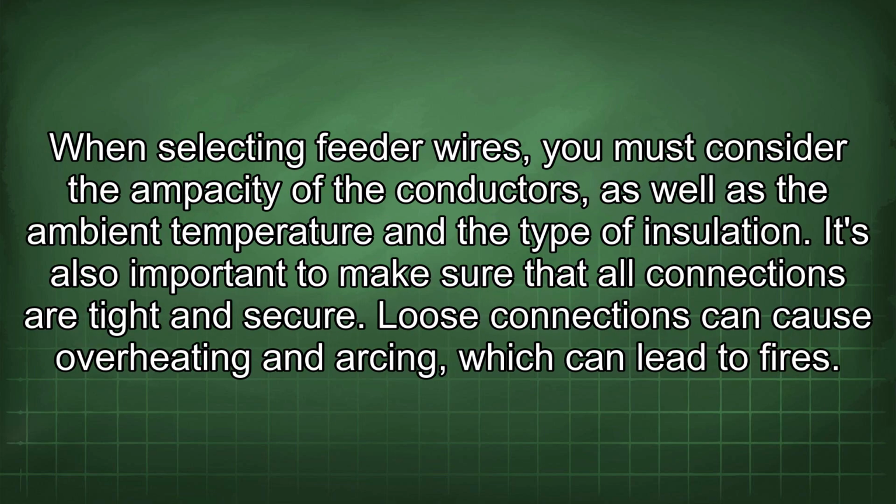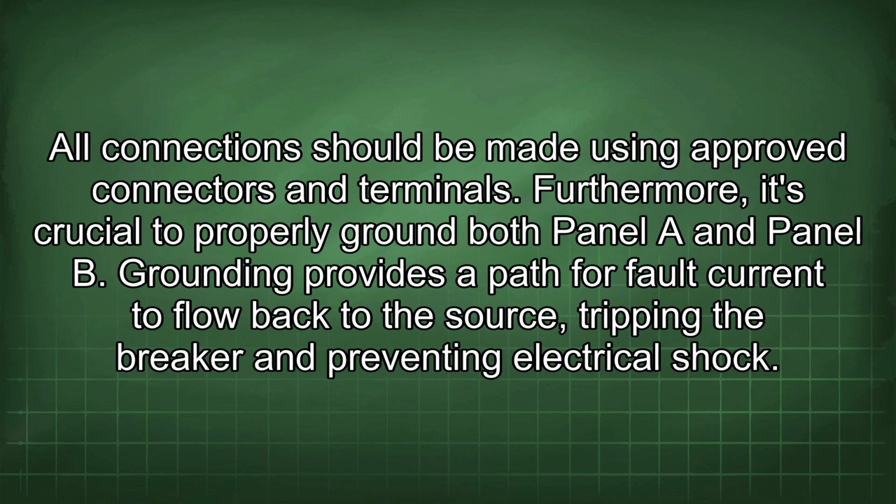When selecting feeder wires, you must consider the ampacity of the conductors, as well as the ambient temperature and the type of insulation. It's also important to make sure that all connections are tight and secure. Loose connections can cause overheating and arcing, which can lead to fires. All connections should be made using approved connectors and terminals.